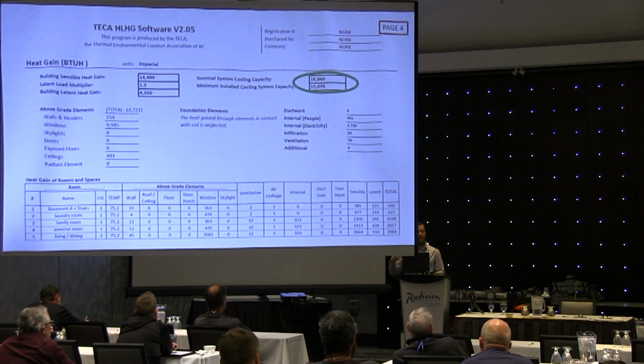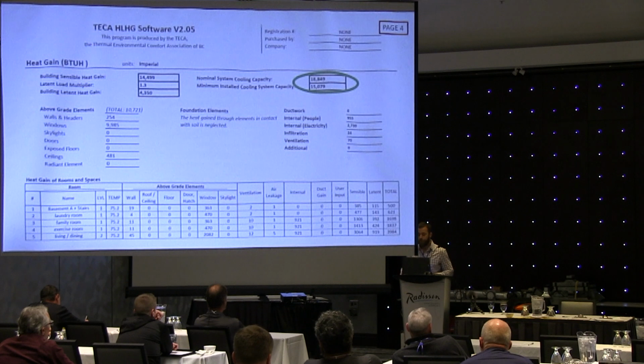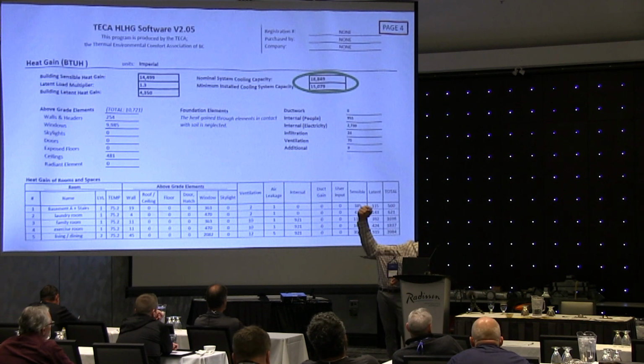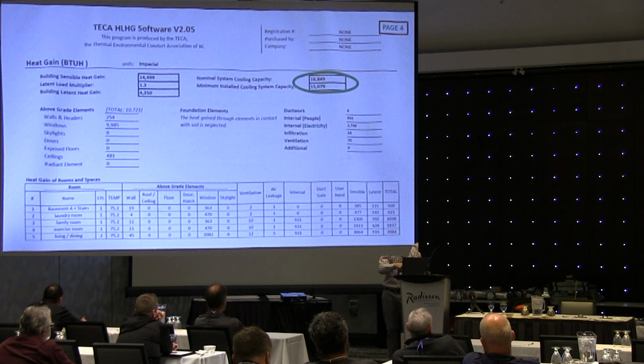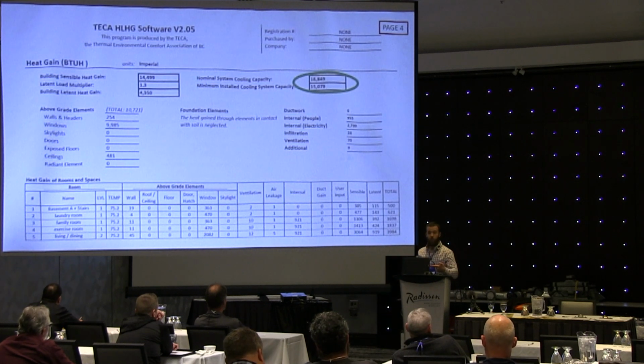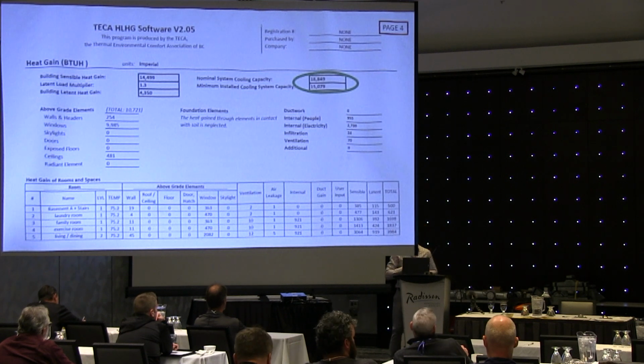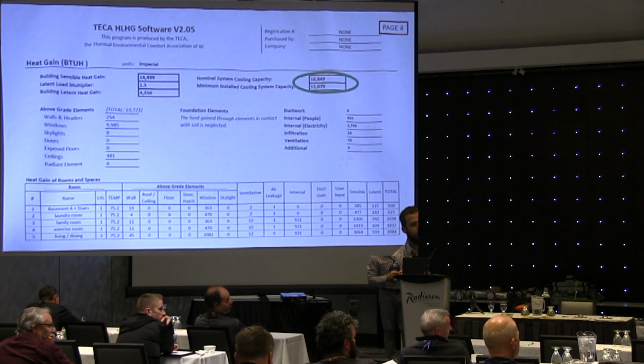When I calculate my heat gain through windows and walls and everything, it's based on worst case scenario. If I've got an east-facing window, the load I calculate for that window is when the sun is coming from the east, shining right through it. But when I calculated my west-facing window, I did the same thing. I said when the sun is shining from the west, what load is hitting that window? So you're not going to be loading these two at the exact same time. Make sense?